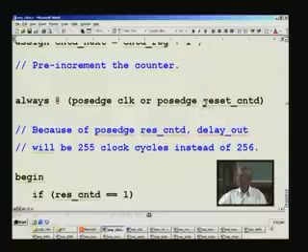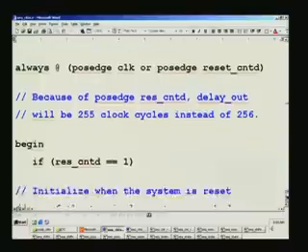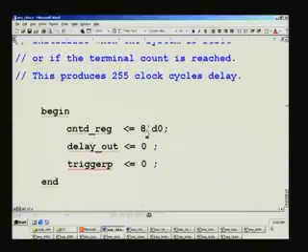So what is put here as a condition is or positive edge of reset control D. So immediately this condition is satisfied and right at the positive edge following that this is also satisfied, so it immediately enters within a nanosecond. So it satisfies this condition and then goes on to clearing the counter itself, right. That is precisely what you have, and simultaneously delay out is also made 0. That is how you get that.